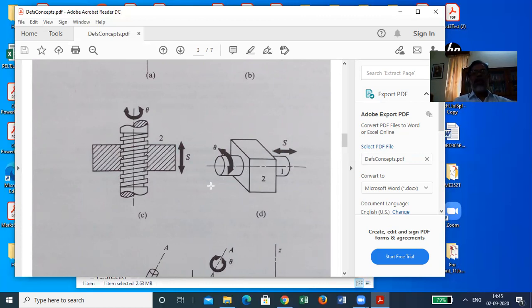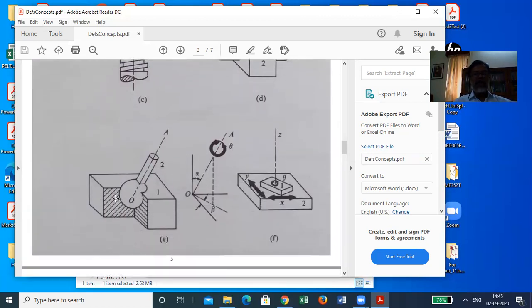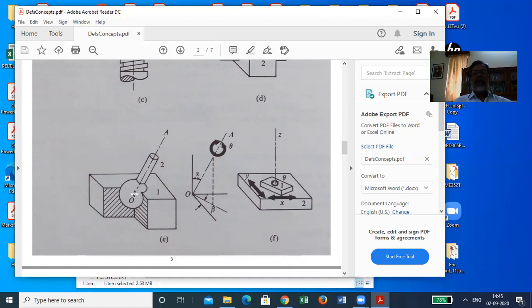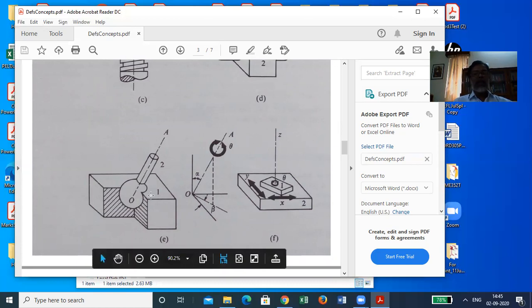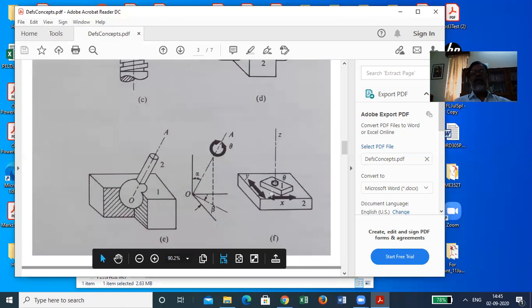Here both the axial translation and rotation are independent. So it's a cylindrical pair, and this is the typical ball and socket joint. Okay. Correspondingly, the spheric pair. So one side of it has been cut to show you how it looks inside. Okay. And this ball can rotate in all possible ways inside the socket without going out, because more than half of it will be actually inside as you supply this quarter also. Now this is a planar pair. Okay.